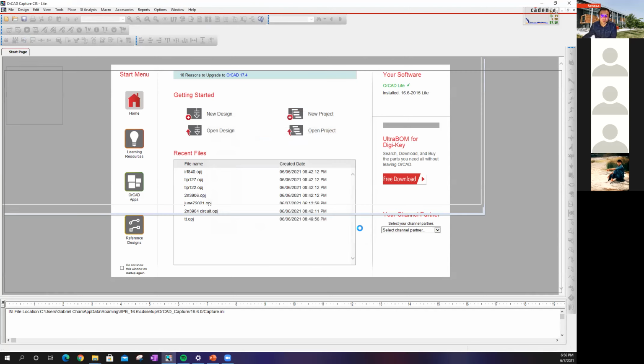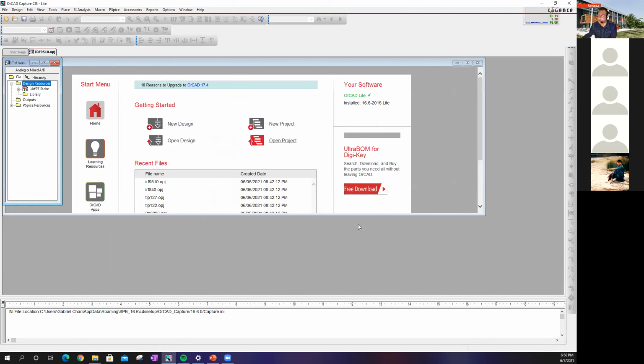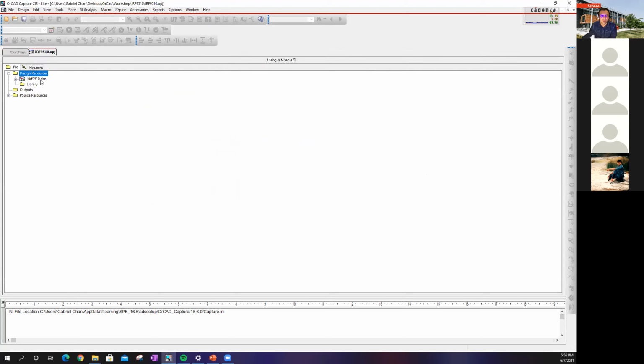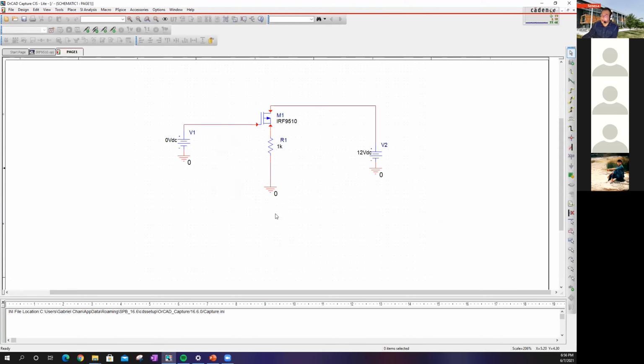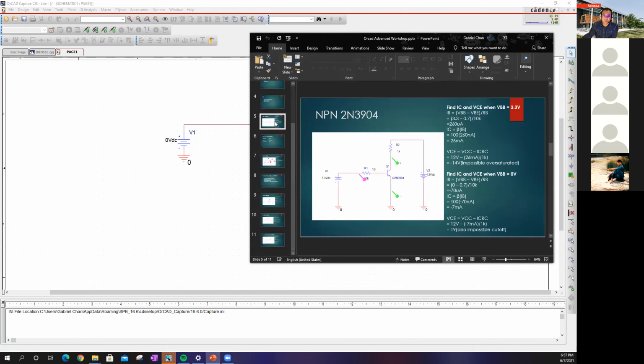905, and then there is level shifting, which is like super complicated. I can go over that too if you guys want me to, but I think we're casual also. And yeah, and then you see the schematic for this. They are pretty simple. It's more simple for voltage driven, as you can see, because you don't really need a current limiting resistor compared to the PNP and the Darlington, like the BJTs and the Darlington. So you can see compared to this. See, there's a current limiting, there isn't.